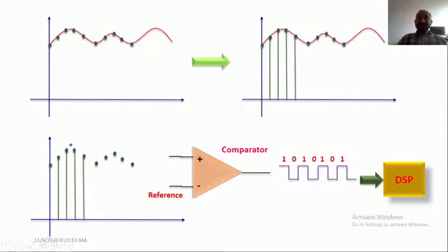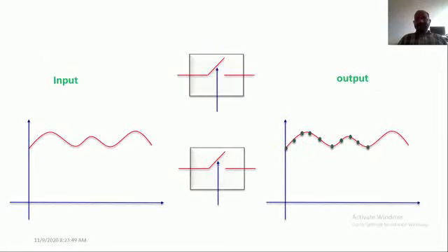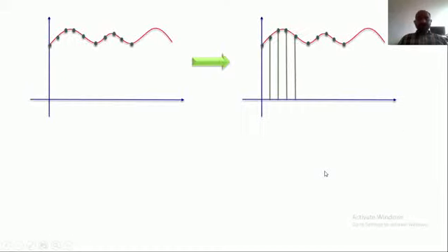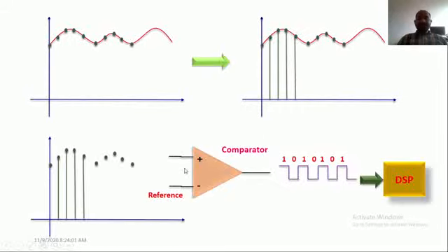How exactly is this continuous signal converted into the discrete signal? That is done with the help of the switch. With the help of this particular switch, we are converting the analog information into the discrete format, the analog signal into the discrete signal. And now this discrete signal is converted into the square wave, that is a digital signal format, with the help of the comparator. These discrete signals are fed as an input to the comparator. So I'm using the op amp as a comparator.